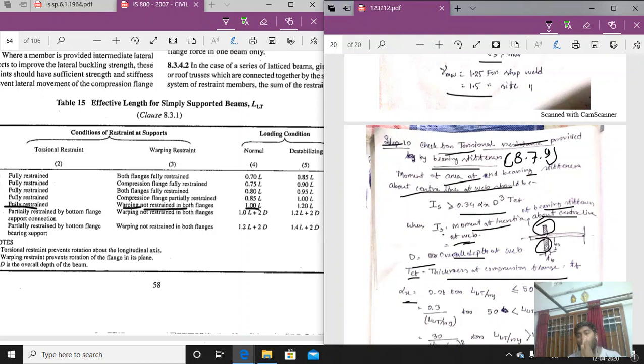Okay, so this is the design procedure for a plate girder. Please go through all the steps very carefully, and remember how all the steps come and how the design steps go. Stiffener design, web plate design, flange plate design, moment capacity check, shear capacity check, and the torsional resistance design. All the checks are to be done properly. Then only the plate girder design will be completed. So we will see one math in the next class. This is up to today's class. We have seen how the design steps help us to design a proper plate girder. So this is for today's lecture.